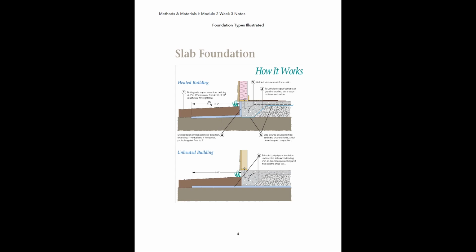And this is a foundation of a house where there's no basement. So literally all they do is pour the concrete slab directly on top of the grade, okay? They don't really excavate down at all. They just basically put it right on top, and then you can see it goes down a little bit, but not nearly as much as it would for a regular foundation. And then they just build the superstructure of the house directly on top of that.